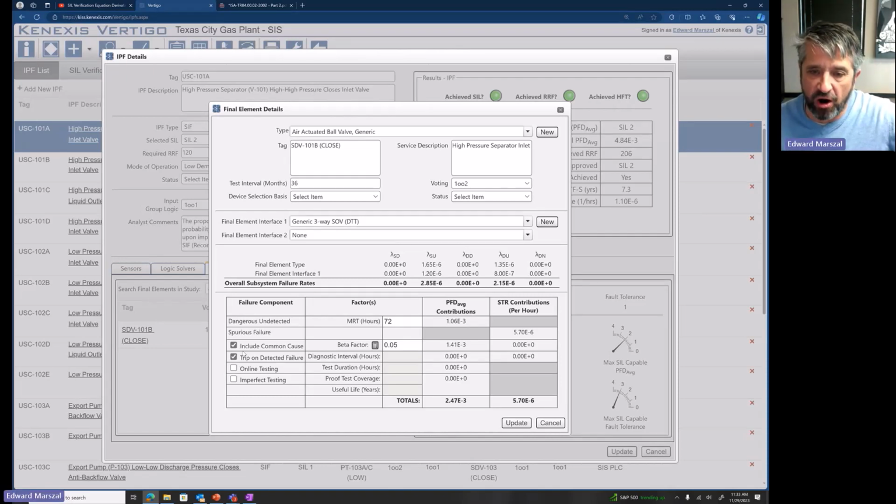Initiating events are discrete, infinitely short points in time. So each LOPA scenario is a trigger and then the activation or failure to act of one or more independent protection layers. Every initiating event for every LOPA scenario is completely stochastic, completely independent, completely isolated.